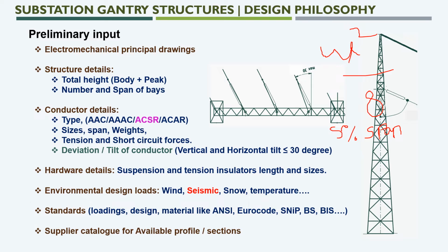So likewise we can calculate the tension values initially. It also depends upon the area and the stress value which is provided by the conductor manufacturer. We can also find the tension value this way. It's nothing but applying the stress value multiplied with the net cross-sectional area of the conductor, and we will get the tension value.